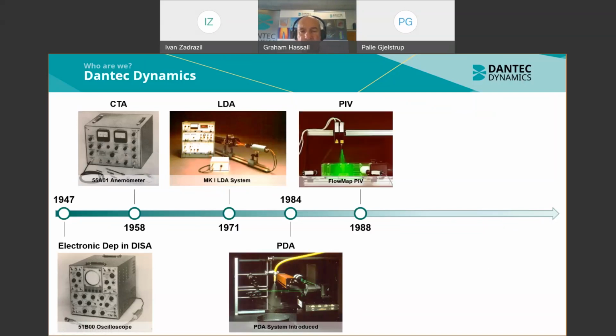A little like hot wire anemometry, one application that could not be addressed by LDA was the measurement over an area or volume at an instant in time. To an extent, this can be addressed with a rake of hot wire probes or laser anemometers, although the laser option would incur a significant cost.